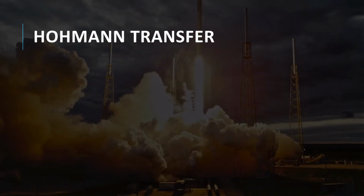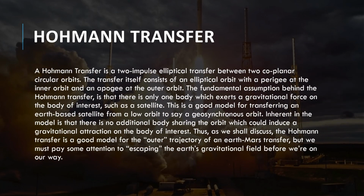Here we come to our first topic, which is the Hohmann transfer method. The Hohmann transfer orbit is a fuel efficient way to transfer a spacecraft between two circular orbits in space. The main aim of this method is to reduce the fuel usage. It involves two engine burns. The first moves the spacecraft from its initial orbit into an elliptical transfer orbit, and the second adjusts the spacecraft speed and transitions into the desired circular orbit at the destination.